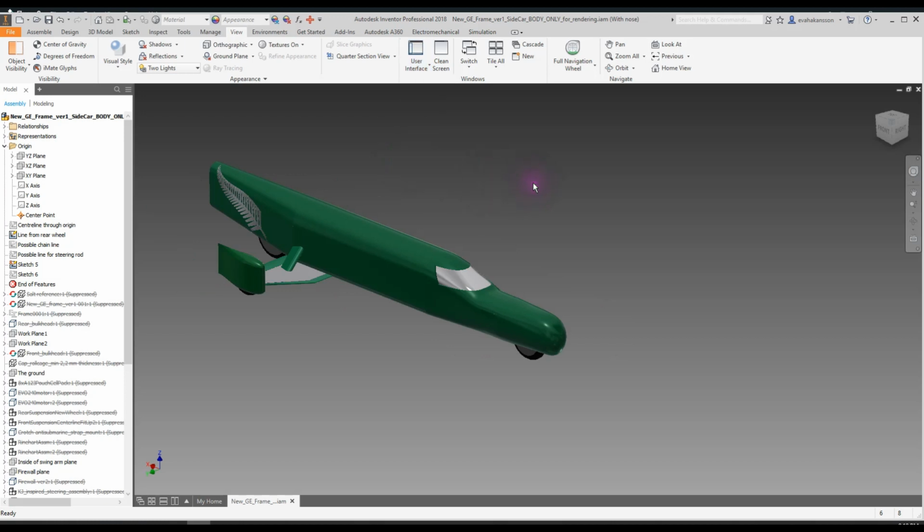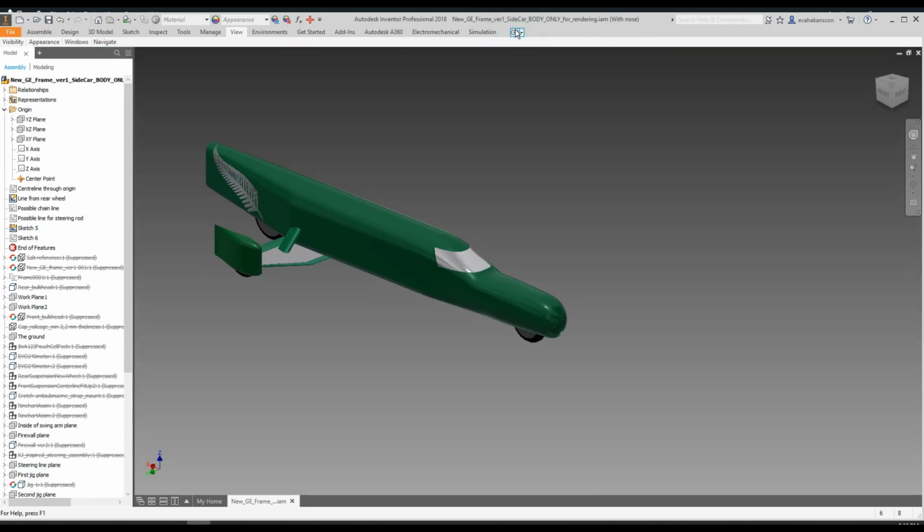Even more scary is if you accidentally remove the ribbon. So it suddenly looks like this, because now it's almost impossible, or at least in my opinion, to find any of the commands. Again, if you restart Inventor, it will remember your settings, so the ribbon will still be gone. The first time this happened to me, it took me almost a full day to figure out what had happened. The key to get it back is this little button up here.